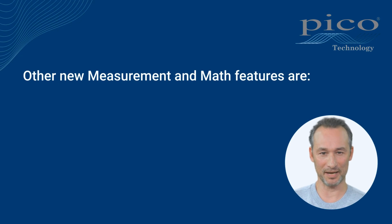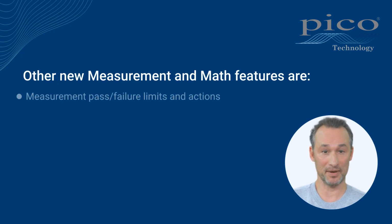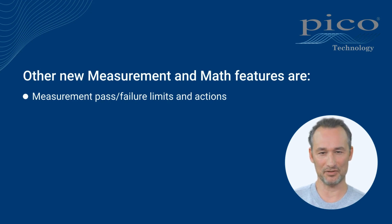Other new measurement and math features are measurement pass, failure limits, and actions. PicoScope 7 offers pass-failure limits for any measurement. This gives a visual indication within the measurement lozenge whenever the signal goes above and/or below a specified value. Pass-failure limits can be combined with actions to alert the user or utilize other actions when a measurement threshold has been exceeded above and/or below set limits.